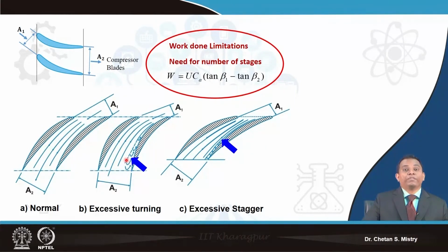If it goes into stall for some time, it will immediately go into surge condition, and there may be chances your engine will fail. So that's why I say the compressor is the heart of the engine. If it is not working fine, your engine is of no use.